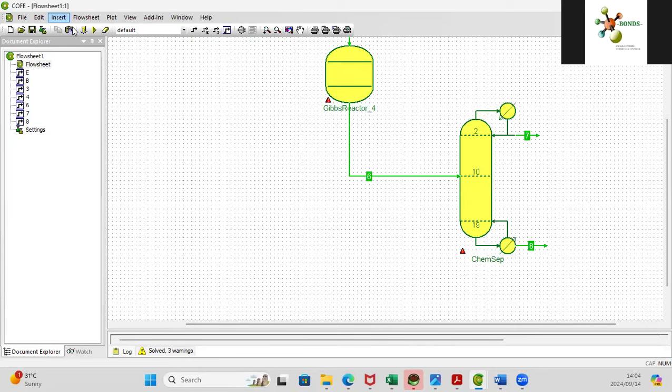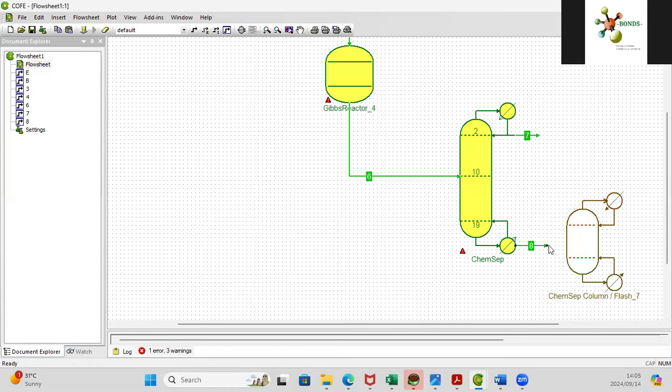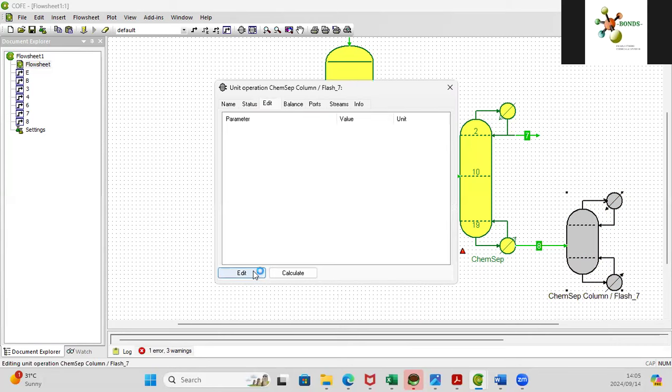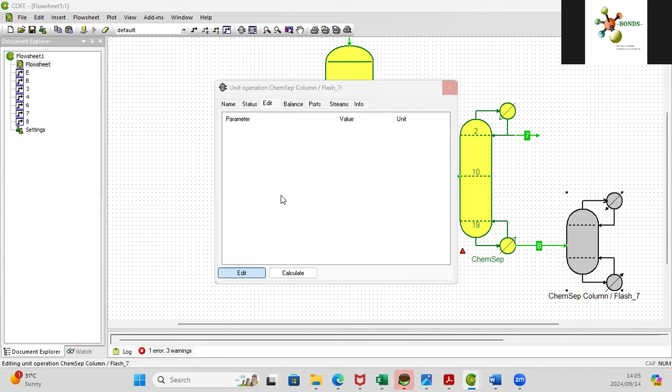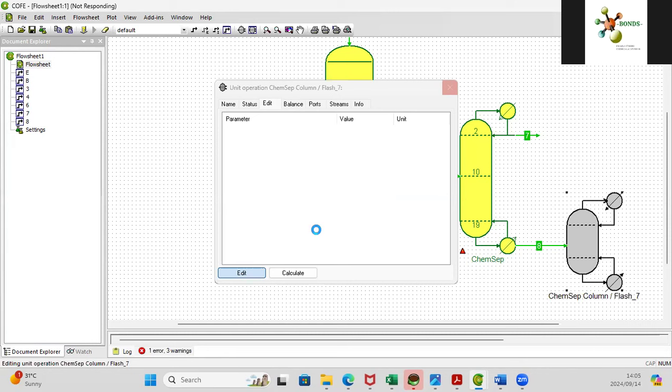I do not think we still have a lot of time here, but hopefully we'll be able to finish. I'm hoping that because we already showed this particular simulation how to deal with our three component mix, it will be able to automatically do that for this column. Again, as a student, please do explore other ways to set up your distillation column. Look at using reflux ratio. On my side, I'm just using component recovery because that's a shortcut method. But look at your distillation column on your simulation.